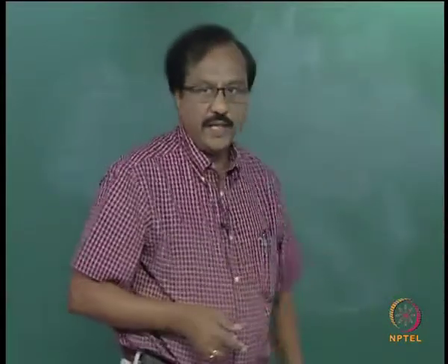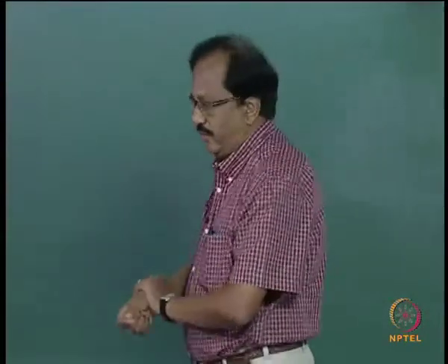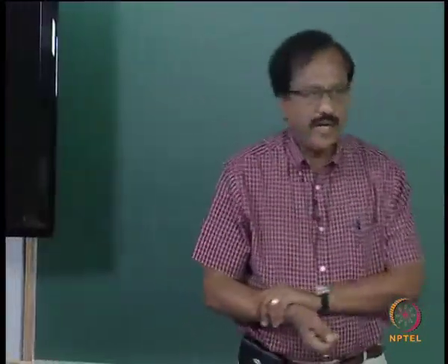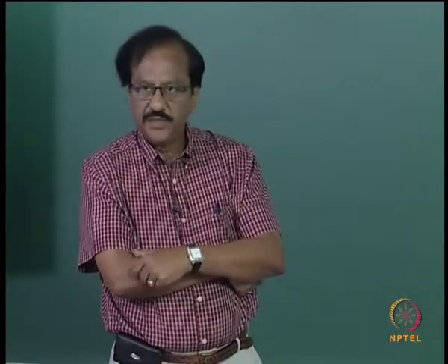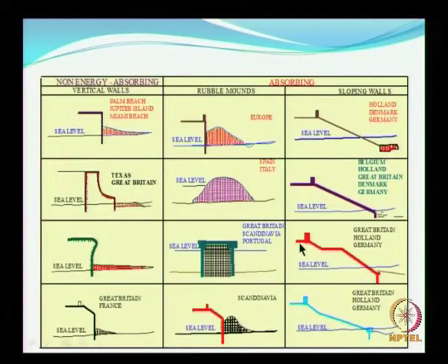When you see later how a sea wall breaks, it will break by what is commonly known as slip circle, which we will see later. So, adopting that, which I will explain later, they have proved that having a berm as shown here has proved to be more stable.